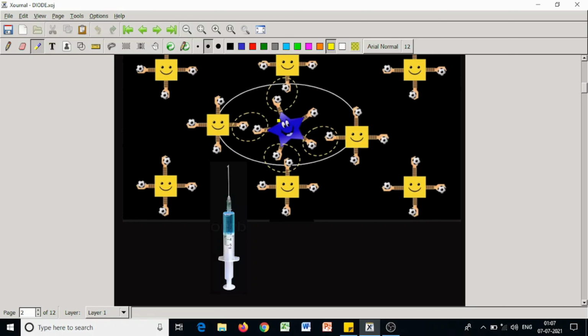In addition, there are free electrons and holes due to thermal breakage of covalent bonds. Here electrons are majority carriers and holes are minority carriers, since holes are extinguished by recombination with the large number of free electrons present in the n-type semiconductor.